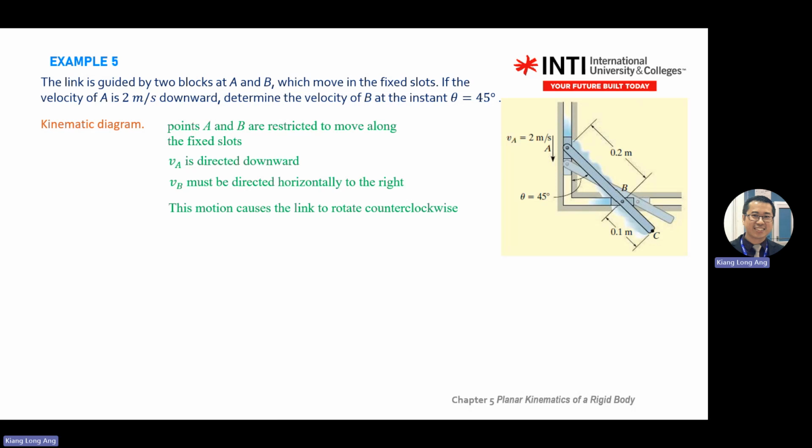So same, you link with these two equations, V equal to omega R. You have tangent and normal directions: A_T equal to alpha R, A_N equal to omega square R. We'll use the right hand rule to determine the direction. So when you rotate this one anti-clockwise, you use the right hand rule, so your thumb points out, perpendicular to the plane of the motion. So your thumb is pointing out, right? This one moves this way.